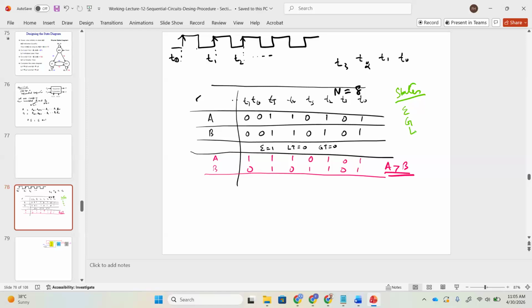Now the thing is, we are getting these bits serially, one by one. These are my states. Let's assume I'm looking at the LSB side: is AI equal to BI or not? This is time t0, and AI is equal to BI. What should be my state now? I don't know the future, and I'm not starting before time t0. Can you tell me what my state should be? Anyone may answer?